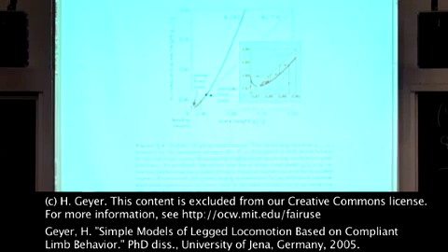But the take-home thing I think that's cool is that even this simplified perspective of it, you get this stability in this conservative system. You get this stability that you can see in the simulation, that even though it's not damping any energy or anything like that, is able to bounce along and right itself. And apparently people didn't used to think that was possible. But the coordinate transform is actually enough to get that kind of stability. It's called piecewise holonomic.